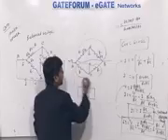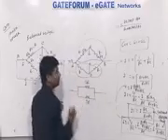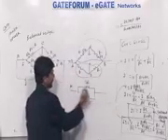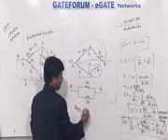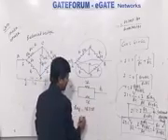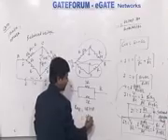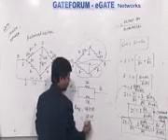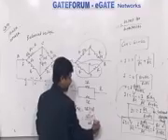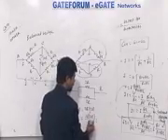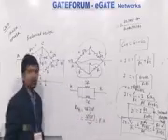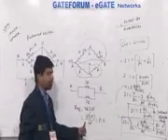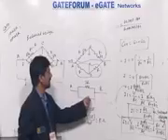So in between A point and B point, R equivalent, RAB is equal to 2R parallel with 2R, which is R1 R2, 2R into 2R divided by 4R, which is equal to R ohm. So I will get the value of resistance is equal to R ohm, which is nothing but half of this 2 resistors.